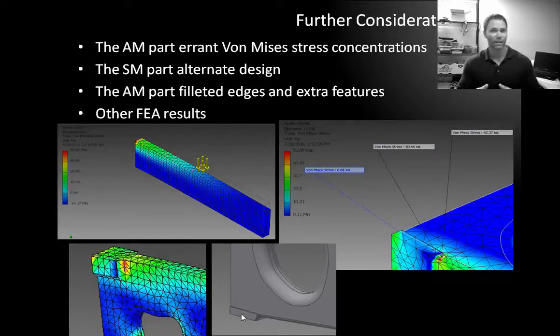Now, with that in mind, the question obviously would be, why didn't you do that for the conventional? Well, that would have required someone to either buy a bigger stock material and cut out a lot of material to get that bump out there and down there, which defeats the purpose of the cost savings with conventional. Or they could have welded it on, which still would have required more labor and more time.